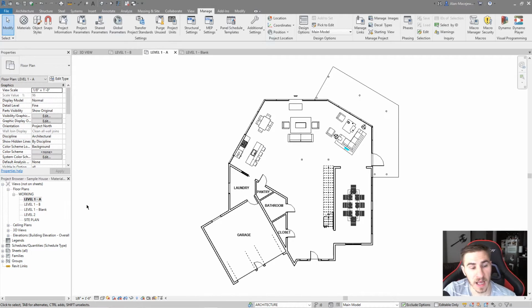So in that case, it would be just fine to not delete that view from a design option, and just have it display the new default for what was accepted as the primary. So I'm ready for that view in that presentation already. I don't have to do anything else. I don't have to remake the views. That's kind of the point.